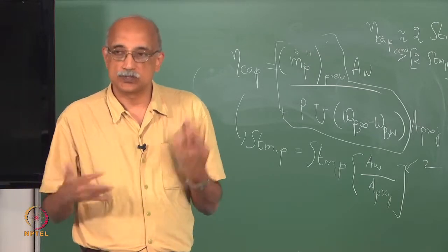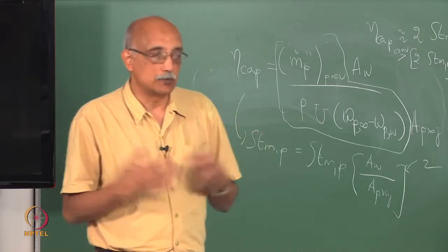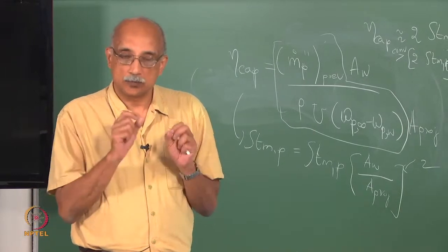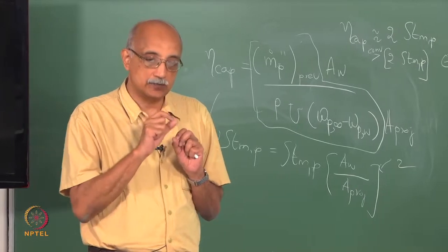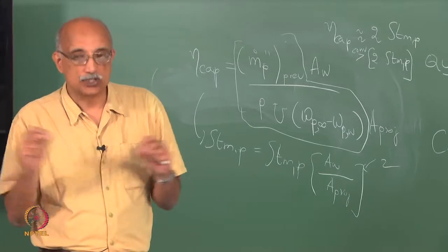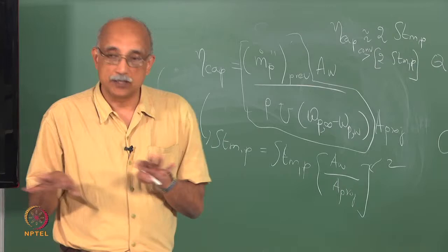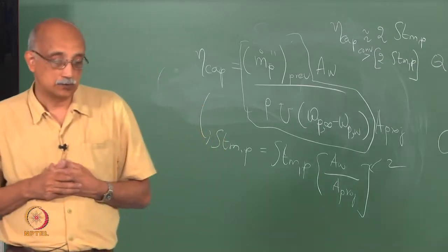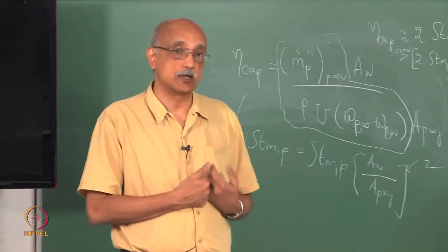So, when you try to do CFD modeling of the flow, you have to deal with it as a 2-phase problem. Whereas, in the case where cohesion is low, you can look at the particles as discrete entities and actually describe the dynamics of each individual particle in terms of their collisions and rebounding and so on. So, there are various pluses and minuses to these 2 types of flow analysis, and also various implications from a process viewpoint. Sometimes you want more cohesive behavior in a flow.